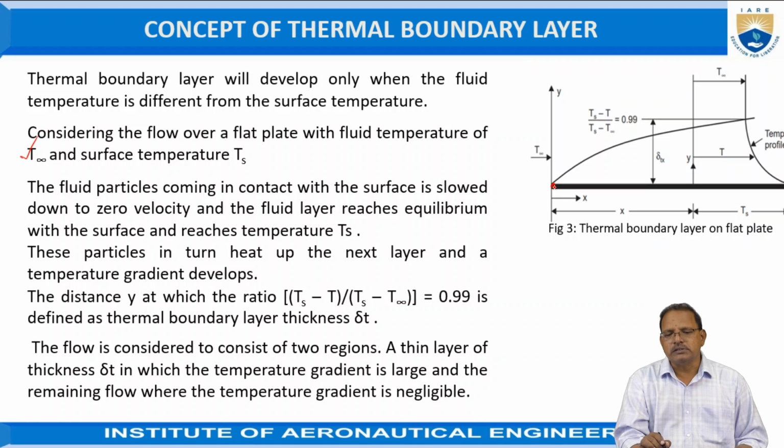Here, when the layer of the fluid touches the stationary plate, the heat transfer takes place from the hot surface of the plate to the liquid surface by using only the conduction process. After that, from one layer of the fluid to another layer, the convection process takes place.